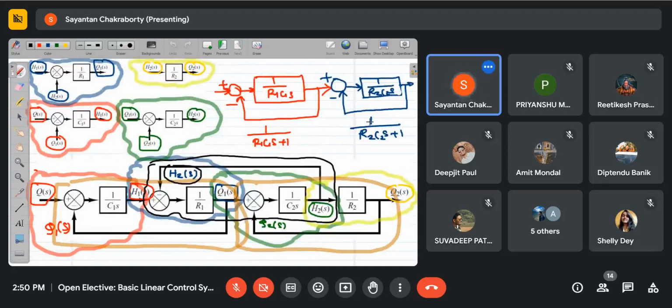This was discussed earlier, right? There are loops, there are internal loops, there are feedback loops, and there are loops that connect. See, this loop is connecting these two internal loops. This is one closed loop, this is one closed loop. But since this loop is present, you simply cannot consider this as a single closed loop because this is also there. So we have to acknowledge the presence of this takeaway point, and for this loop, we have to acknowledge the presence of this summing point. It's a subtracting point. So how to take care of this sort of representation?